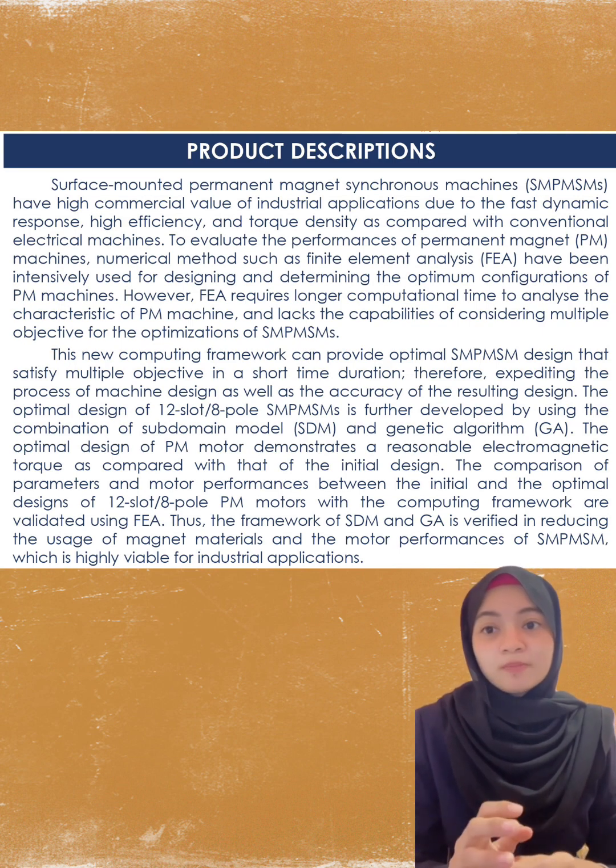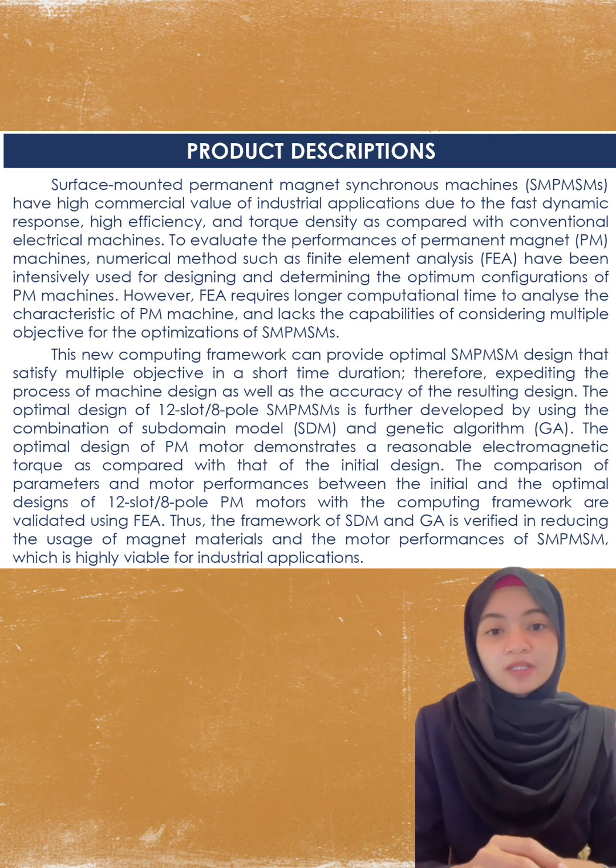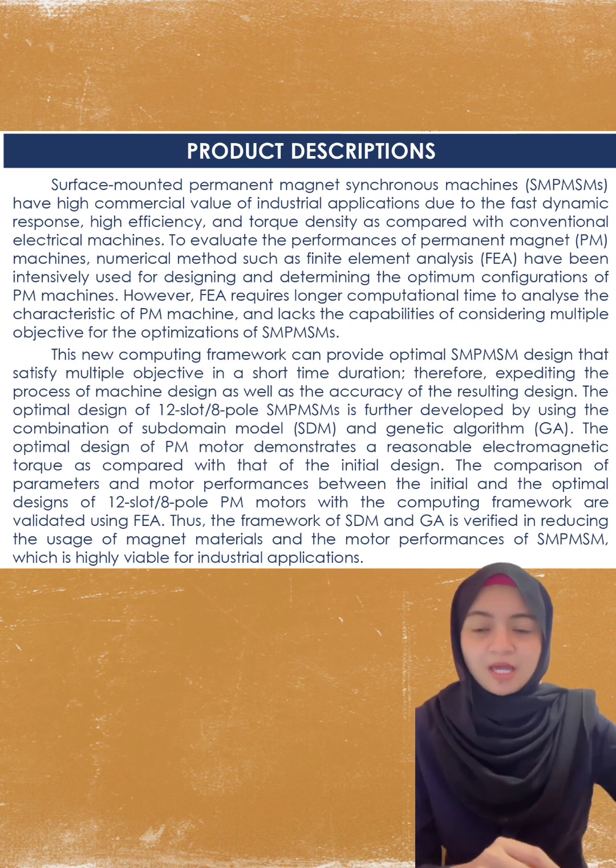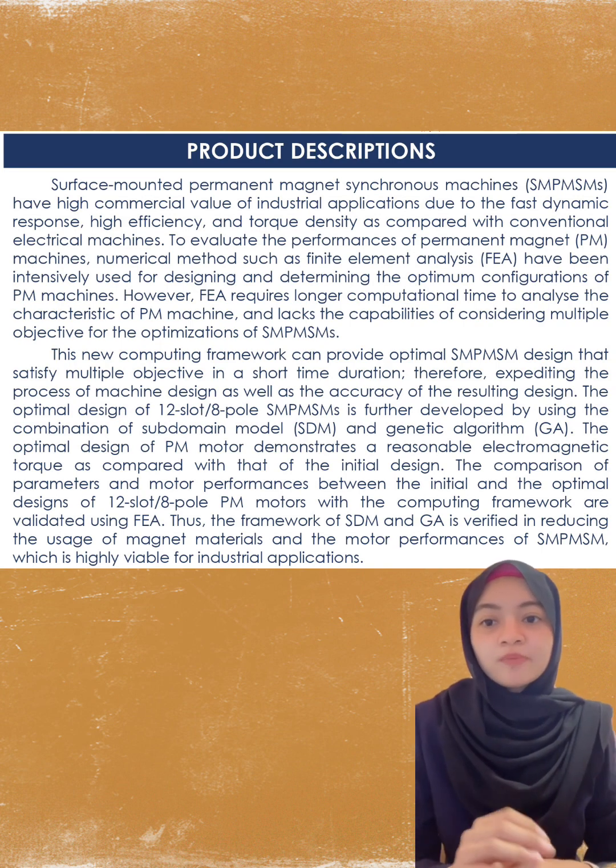In order to evaluate the performance of PM machine, numerical methods such as finite element analysis have been intensively used for design and determine the optimum configuration of PM machine. However, FEA requires longer computational time to analyze the characteristic of PM machine and lacks the capability of considering multiple objectives for the optimization of PMSM. This new computing framework can provide optimal SM-PMSM design that satisfies multiple objectives in a short time duration, therefore expediting the process of machine design as well as the accuracy of the resulting design.